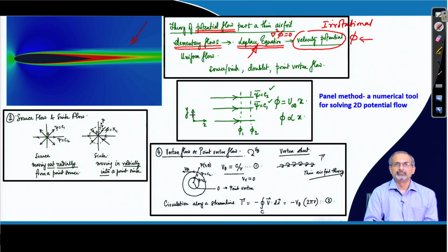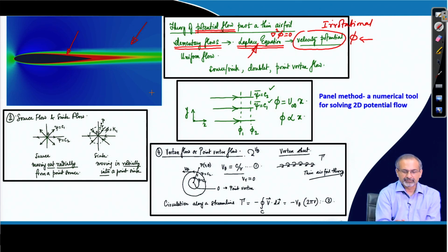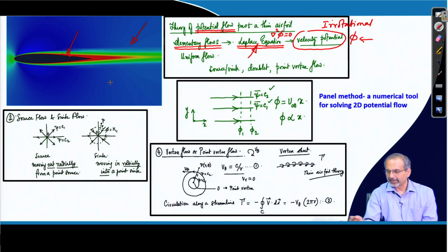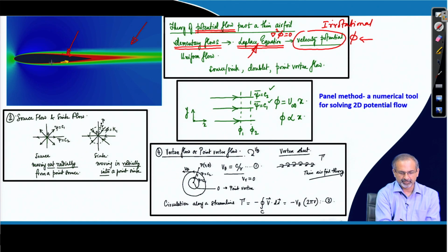by applying suitable boundary conditions. And you need to know that if you are solving potential flow past an airfoil, what kind of boundary conditions are you going to apply? For example, you remember that this is an inviscid flow, therefore, the flow can slip on the body. So, the flow can have a tangential component on the surface, right. So, it can slip like this because you are discussing inviscid flow, but it can never penetrate the surface. So, this is not at all allowed. Normal component of velocity has to be 0.